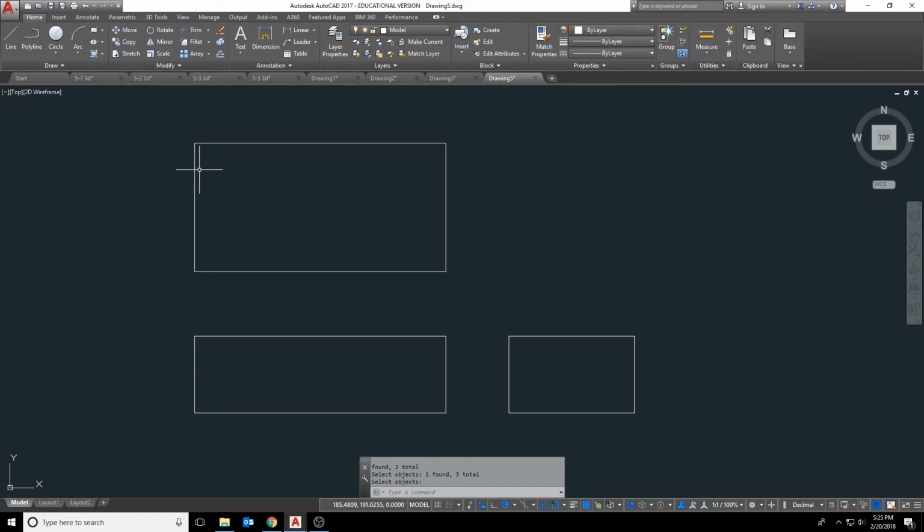The first thing I want to do is start with the front view. I know that this L shape that is going to exist in here is going to be the same on both sides. So I'm going to do it on one side, and then I'm just going to offset it for the other side. To start this, I'm going to go to the line command. I'm going to come to this endpoint, and hover and then move over so that I can track off 30 millimeters. That's going to give me the first point.